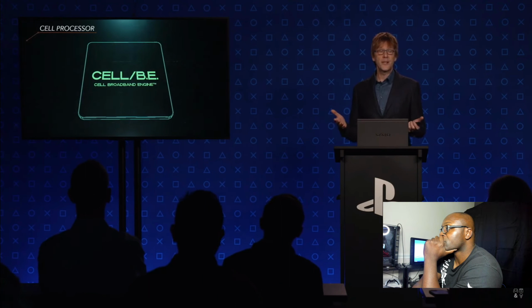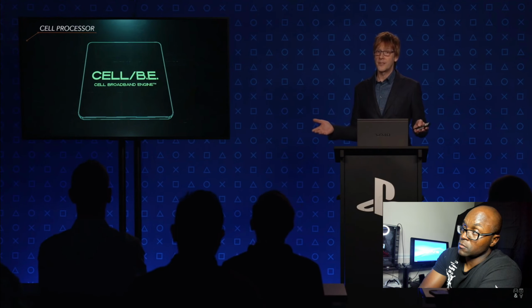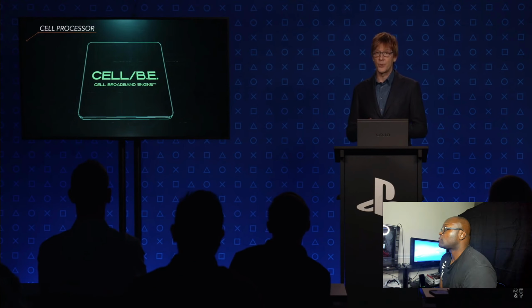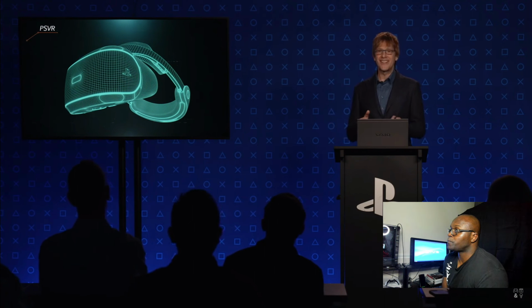The SPUs in Cell were almost a perfect device for audio rendering. Simple pipelined algorithms could really take advantage of asynchronous DMA and frequently reached 100% utilization of the floating point unit. There's unfortunately nothing comparable on PlayStation 4. Probably the most dramatic progress in the PlayStation 4 generation has been with virtual reality. The PSVR hardware has its own audio unit. It supports about 50 pretty decent 3D sound sources. And this provided a hint as to where we could go with audio, as well as some valuable experience.